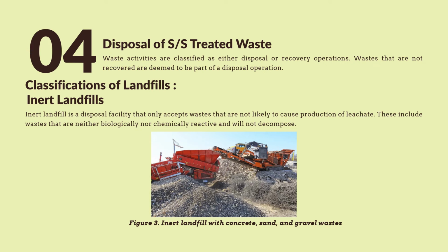For inert landfill, it is a disposal facility that only accepts wastes that are not likely to cause production of leachate. These include wastes that are neither biologically nor chemically reactive and will not decompose. So such wastes are concrete, sand, gravel, metal scraps, and asphalts.